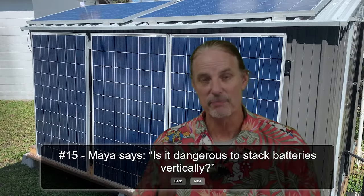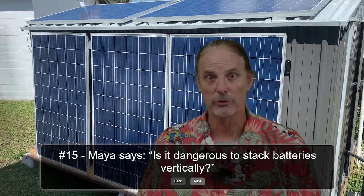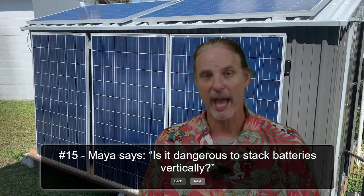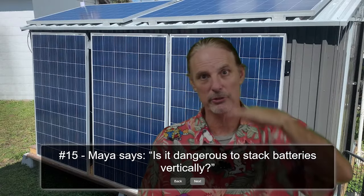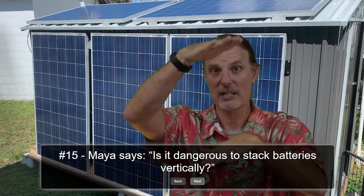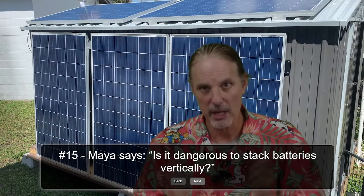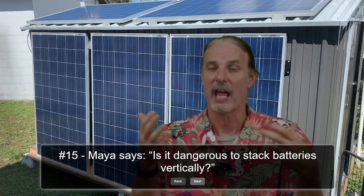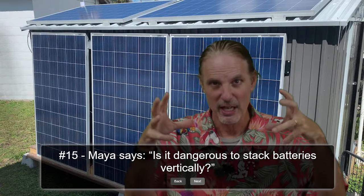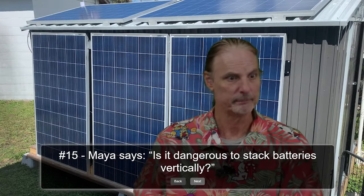So you do need to be very careful of the battery manufacturer specs of how those batteries can be laid. Most lithium iron phosphate batteries don't matter if they're sitting up or on their side. As far as stacking them on top of each other, that is a completely different question, and you would want to check with each manufacturer because the cells themselves matter, the batteries matter, and the infrastructure and the way the batteries are built are going to have a difference in this particular case. All right.